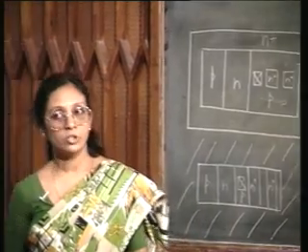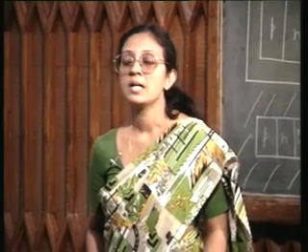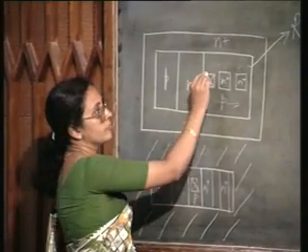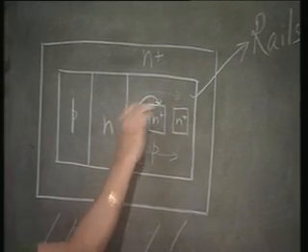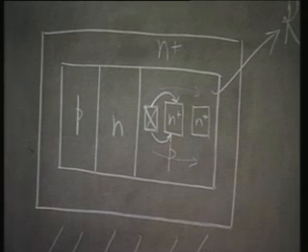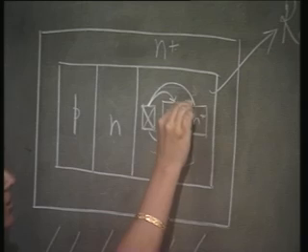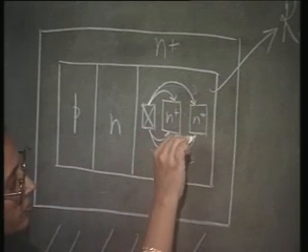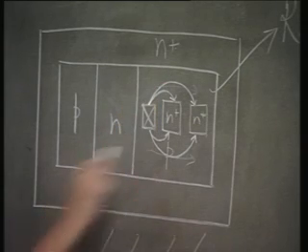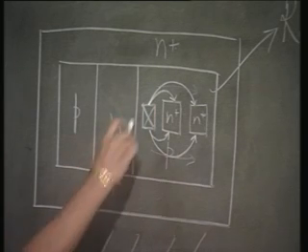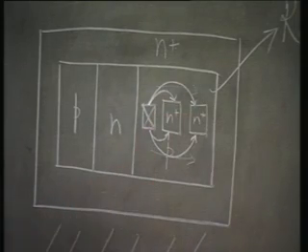But even though space saving is a great advantage, the oxide isolation case does have a small problem. And what is that small problem? Look at the way the current flows from the base to this. I have to have multiple collectors in the I square L. Multiple collector means I have so many fan outs. Okay. So, the path of the current in this case is like this. Current can flow through the rails. I have P regions on both sides which are the rails, and the current can flow, go to the second collector, to the third collector through the rails.